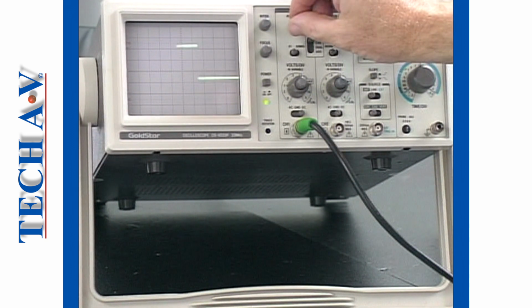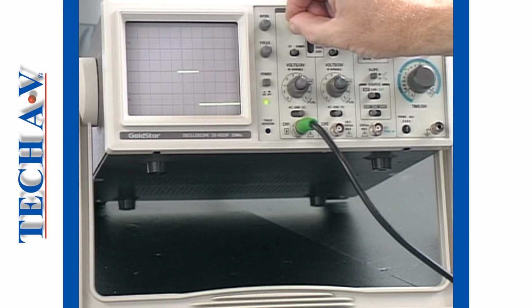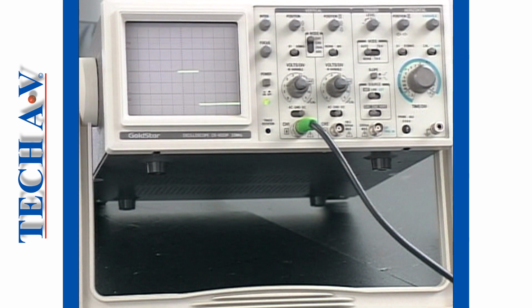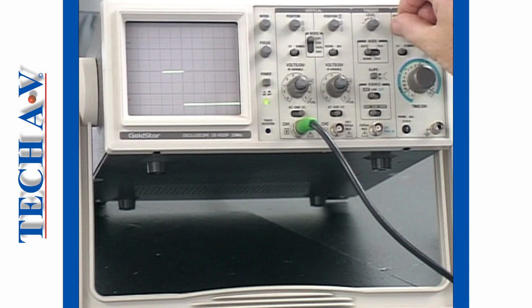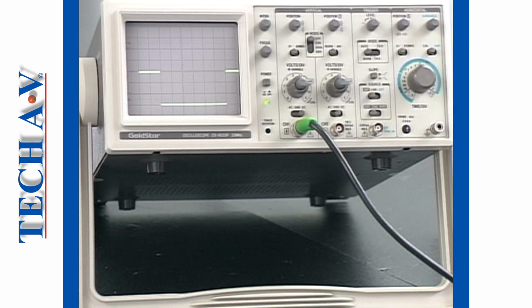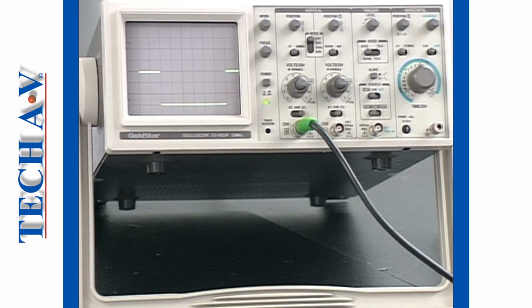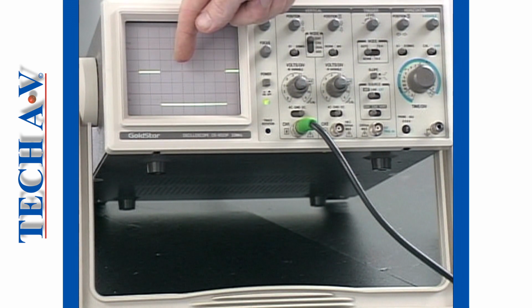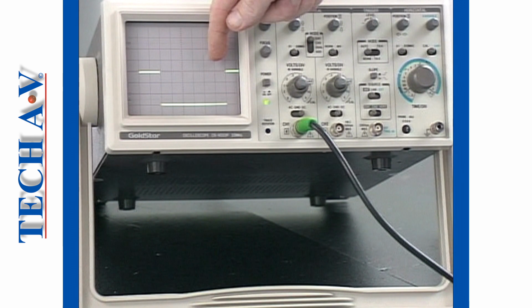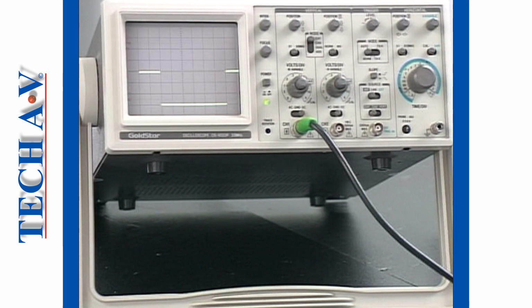To measure the length of the mark, superimpose the top edge of the pulse on the horizontal center line. Position the leading edge of the pulse on a convenient vertical line. Count the number of divisions from the leading edge to the trailing edge of the pulse. Now count the number of divisions between the trailing edge of one pulse to the leading edge of the next. This will be the duration of the space.